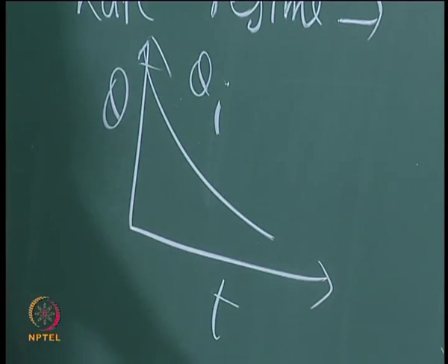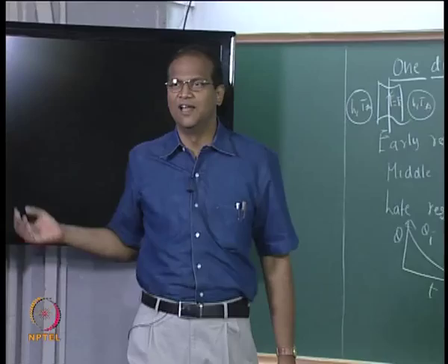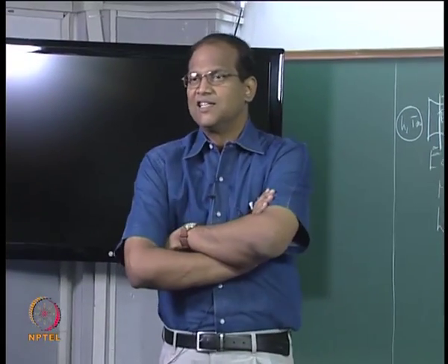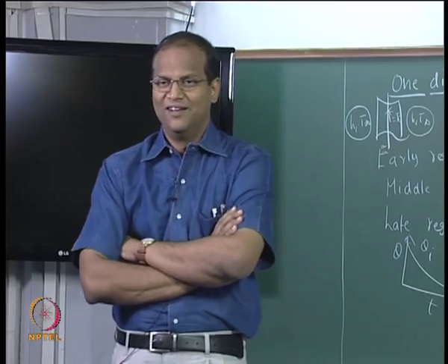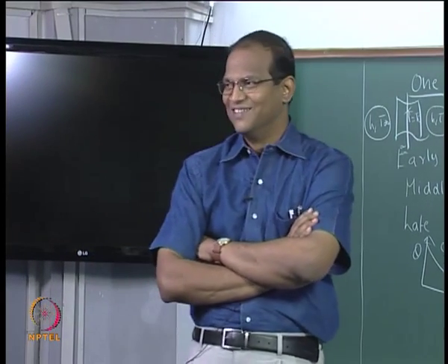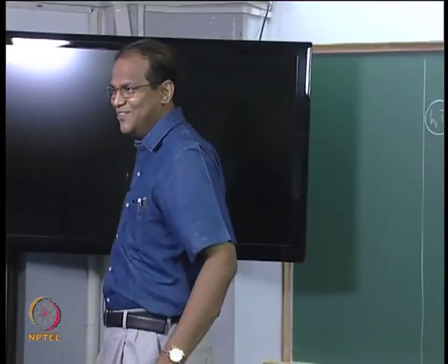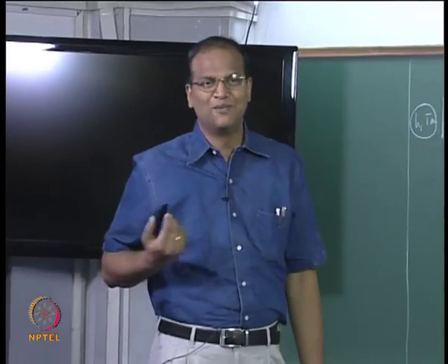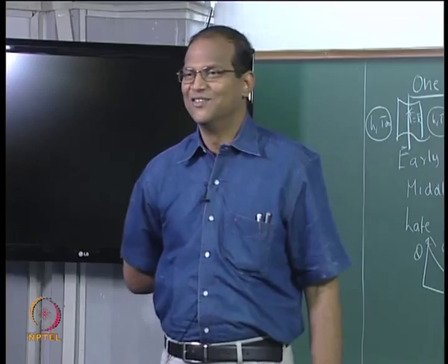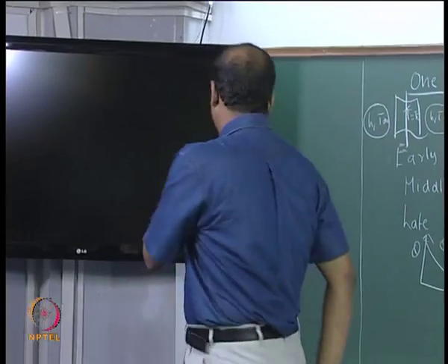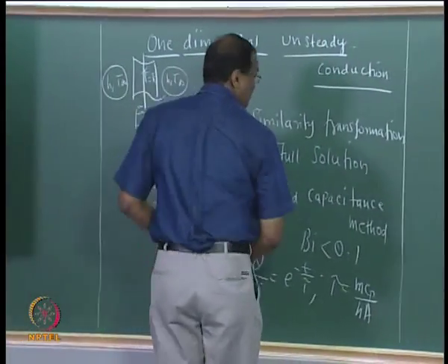Even if you plot, a lot of systems in real life follow this. If you plot the attendance in this course versus time over the last 10 days, it will follow theta by theta i is e to the power of minus t by tau. So that is a law of nature, exponentially decaying with time. So that is the solution for the lumped capacitance system.